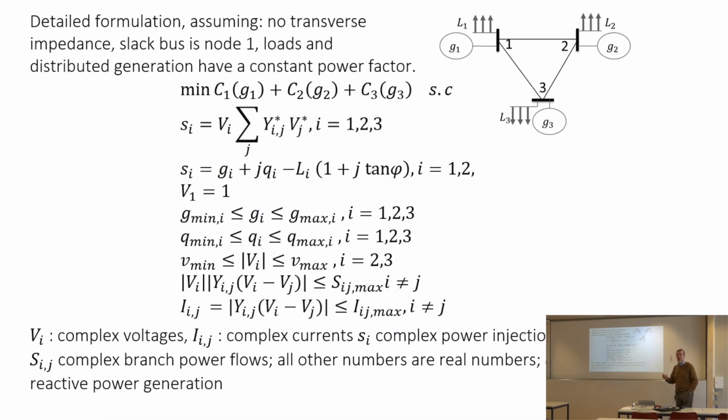At every bus, the sum of the powers that get in is equal to the sum of the powers that get out at a bus, at a single point that has 0 dimension, which is also the sum of the power injected by the generator. That's its active power. That's the interesting power. That's the reactive power. We'll talk more about it in a few more minutes. This is minus the loads.